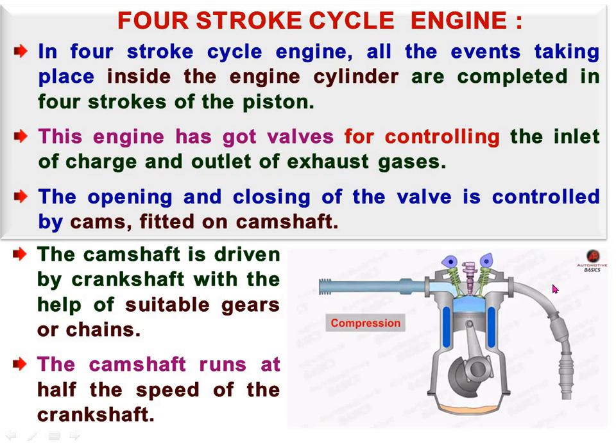So this valve permits the entry of fresh air inside the cylinder. And after the power stroke, as the exhaust stroke starts, the exhaust valve opens, and whatever burnt gases are in the cylinder are expelled through the exhaust valve. At that time, the exhaust valve is open.